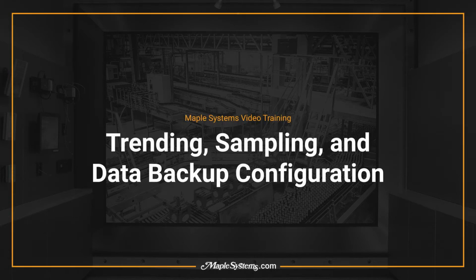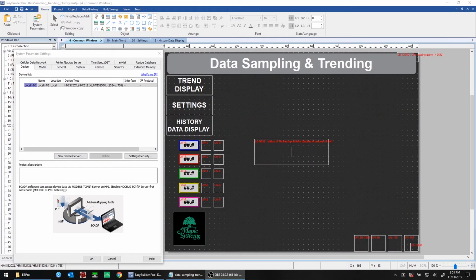In this video, we'll show you how to set up data sampling to collect time series data from a PLC or other device in EBPro, as well as how to create visual representations of this data to add to your HMI screens, these being real-time trend displays and history data displays. Finally, we'll show you how to back up the data the HMI collects using backup objects.